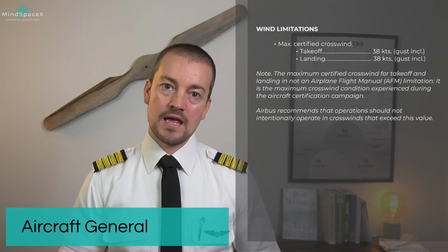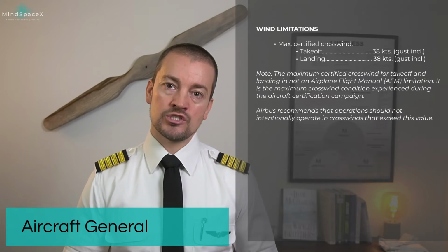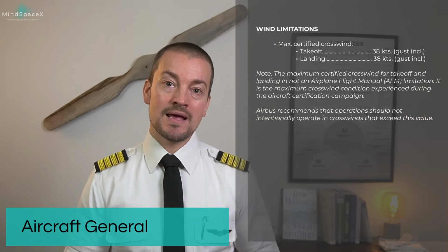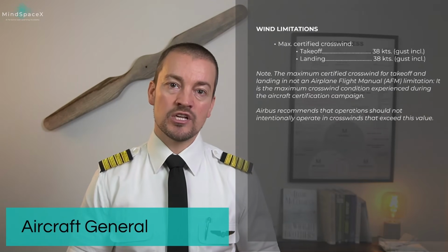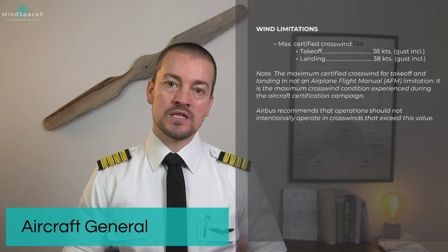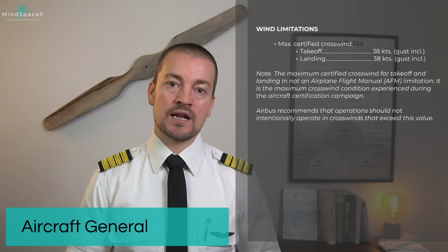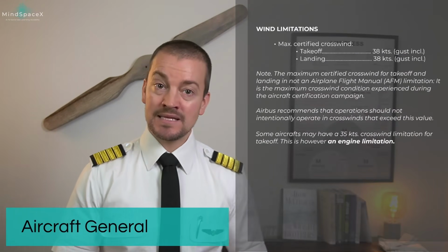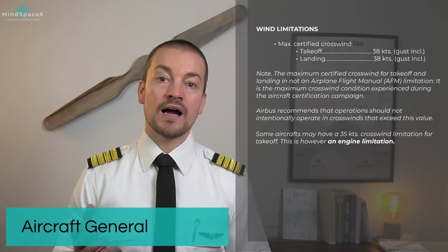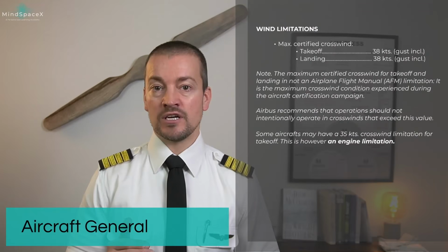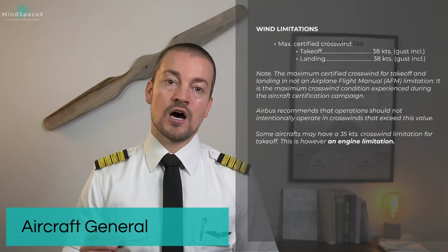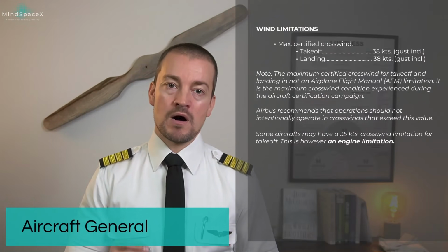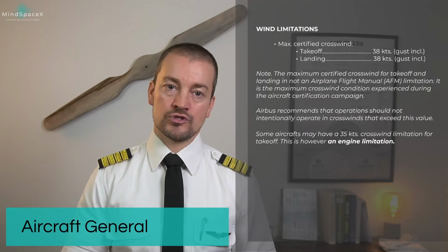It is a maximum crosswind condition experienced during the aircraft certification campaign, and Airbus therefore recommends that operations should not intentionally take place in crosswinds exceeding these values, as this is outside of what the aircraft was tested on. Some aircraft may have a limitation for crosswind of 35 knots. This is, however, a limitation based on engines, not the aircraft. And this is specifically applicable to newer models of engines, so the newer versions of engines.